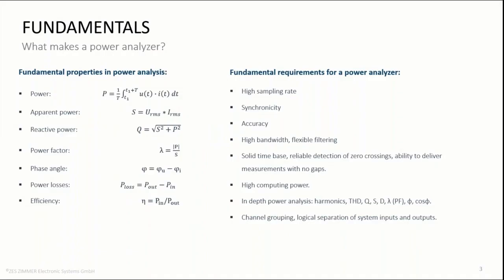Here we see on the slide a part of the measurements that a power analyzer can perform, and these are fundamental properties of power analysis. Now, taking a closer look at the formulas, we can see how certain defining requirements for a power analyzer can be derived from them. Let's, for example, take a look at the active power. Here we notice two things happening, one of them being multiplication and the second being integration.